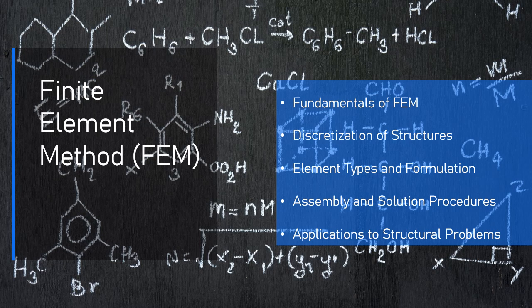Use appropriate material properties for the beam, e.g., Young's modulus, Poisson's ratio. 3. Define the mesh. Select the mesh size and number of elements. 4. Apply boundary conditions. Define supports at both ends of the beam, e.g., fixed support at one end and roller support at the other. 5. Apply loading. Apply the uniform load along the length of the beam.